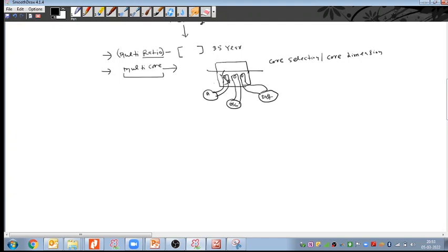Let us make a bus bar, and then it is going to any transformer or any motor, putting a circuit breaker to control this transformer, and now we are putting the CT cores. Suppose we are putting one CT core for metering and a second for protection purposes. So for this metering CT core, what parameters do we have to specify?